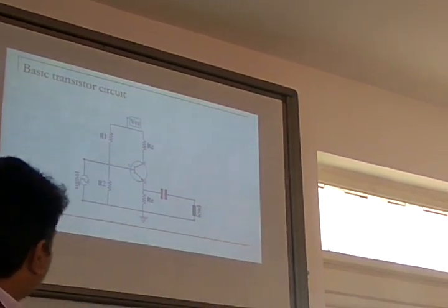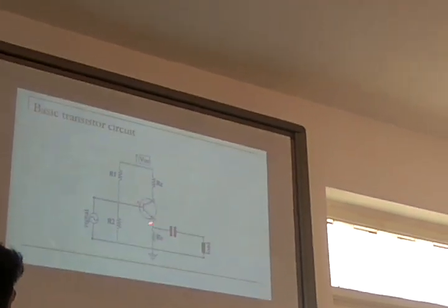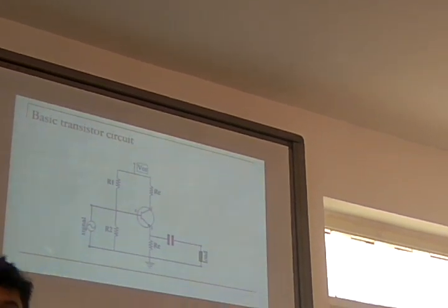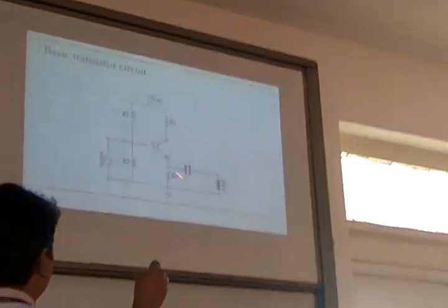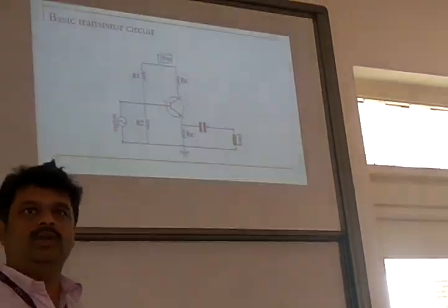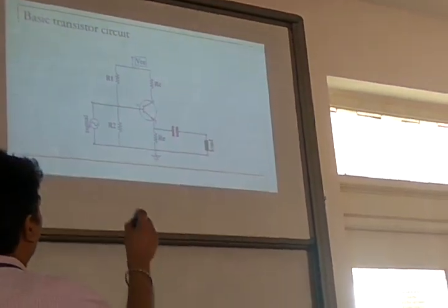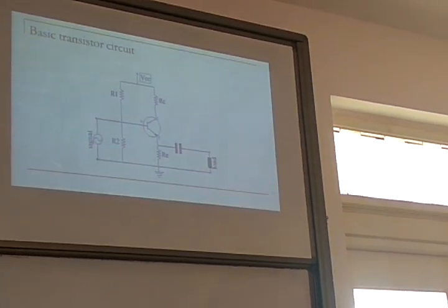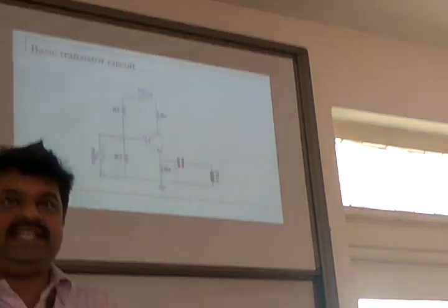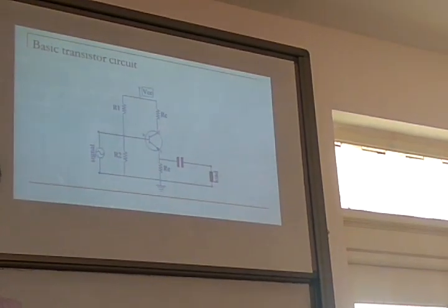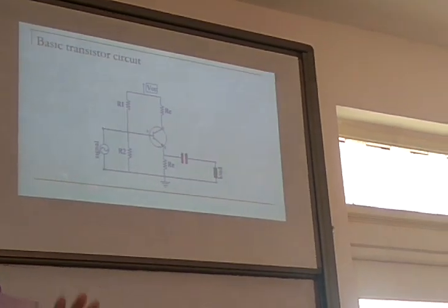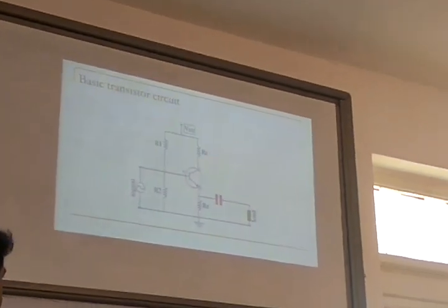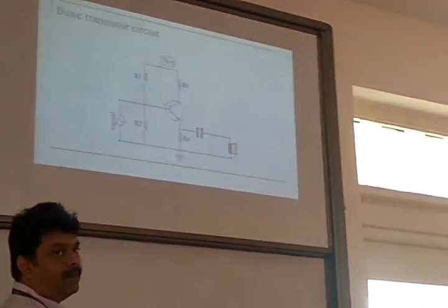So you put a capacitor here. No DC component will come there. Only AC can go there. And all DC will be grounded. It will all go to the ground. Only the AC component will go. Why? My signal is an AC signal. Even if by mistake any DC noise component gets amplified and comes, I simply want to filter it out. I want only the AC variation. Any DC component, I am not interested.